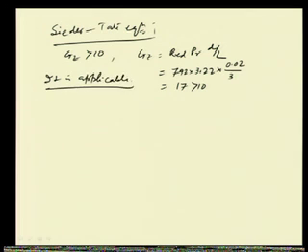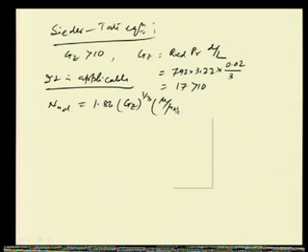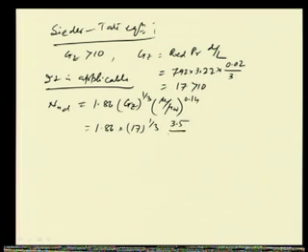Okay. Now, once it is applicable, let us try to find out what the Nusselt number is. Nusselt number is 1.86 into Reynolds, I am sorry, we know already it is Graetz to the power 1/3 into mu by mu w to the power 0.14, and if you put the values here, 1.86 into 17 to the power 1/3 into mu by mu w, that we already know is given as 3.5 by 5.0. I am sorry, it is just the reverse of that.